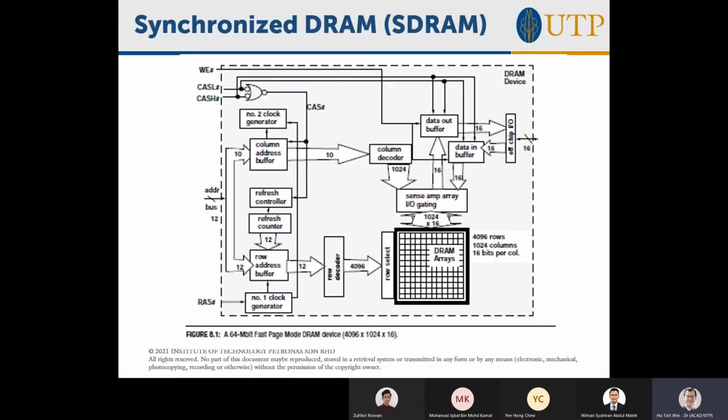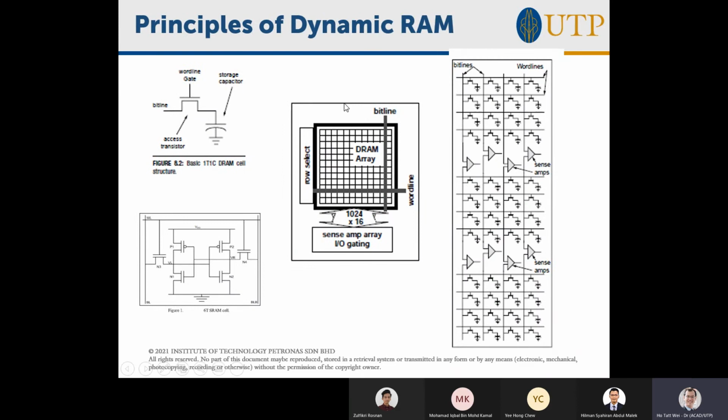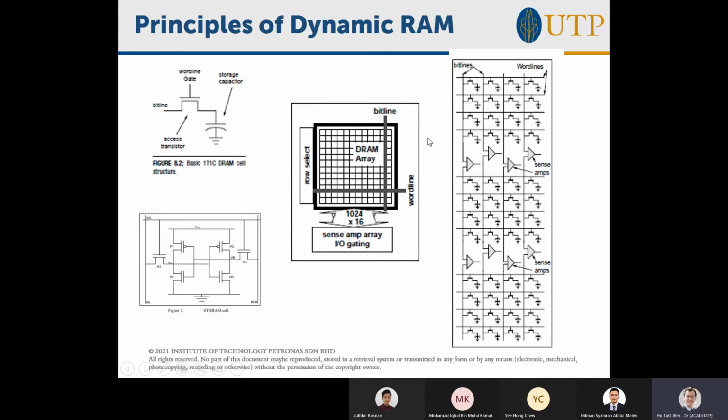The reason is that there is a fixed size at which they can build the DRAM array. Bigger than that, the bit line and the word line capacitance becomes too large, and then it will slow down the chip. Let me repeat that. People are not going to build a DRAM array of 32 gigabits or 64 gigabits. Why? Because there is a sweet spot, a maximum size of your DRAM array.